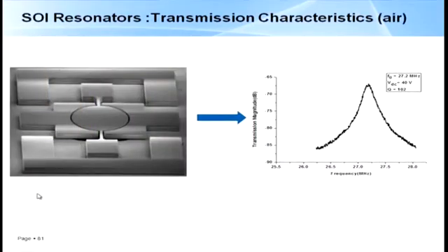Look at it, the structure is only 20 micron by 20 micron. This is a resonating structure, and it offers a quality factor of 100. So you can think of it: if you have just a resonator, you can replace the crystals and make a very good spectrum response.